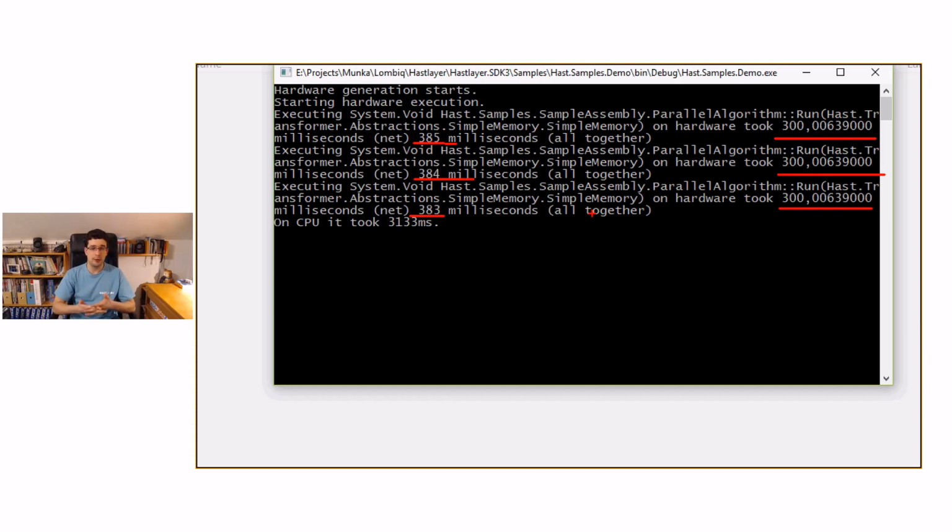Now the difference here is quite big, and the reason is again that this is a slow FPGA port. It just has a USB and an Ethernet port, and we use the USB port here for data exchange, which only offers a quite slow virtual serial connection. But with bigger, faster FPGAs, of course, this latency would be smaller as well, for example, by using PCI Express.